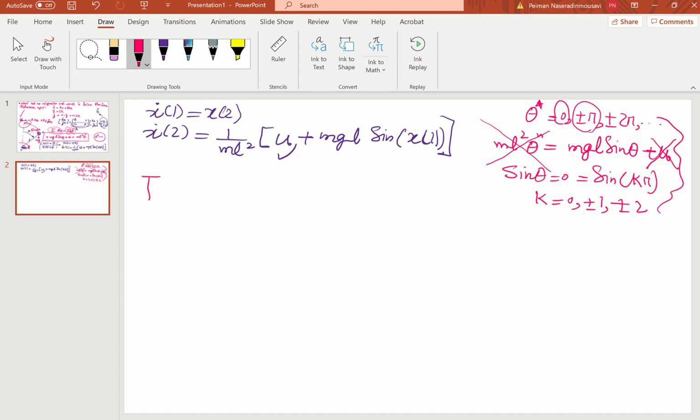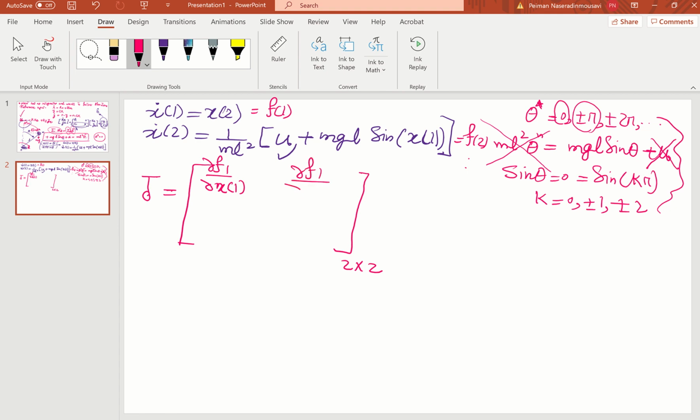You have to make the Jacobian matrix, not the robotics one that I'm teaching this semester. This is the control one, because you have two state variables, you're going to have a 2 by 2 matrix. I taught you previously in this course. It's round f1 over round x1. If this is f1, you have to name it like this. This is f2. Then round f1 over round x2, here round f2 over round x1 again, and the partial derivative of f2 with respect to round x2.